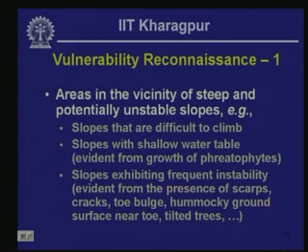There are several different plants that like to grow near places where water is abundant, and they grow near the places where groundwater exits a slope face in many instances. So their presence indicates the locations of potential landslide instability.